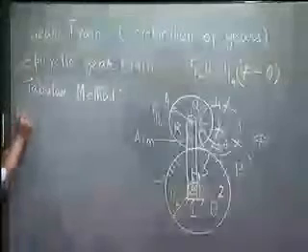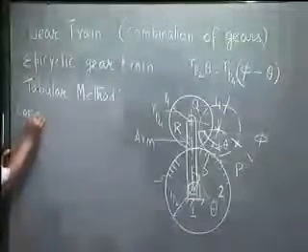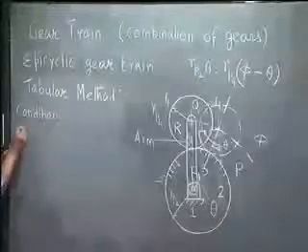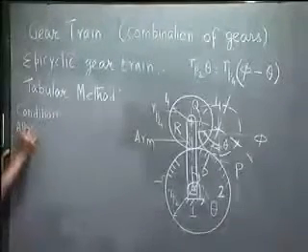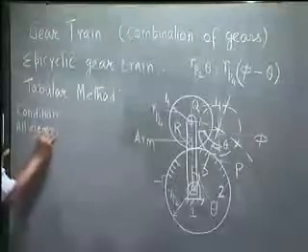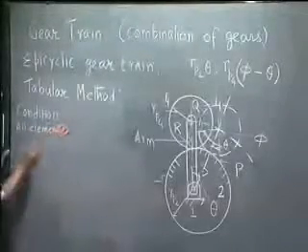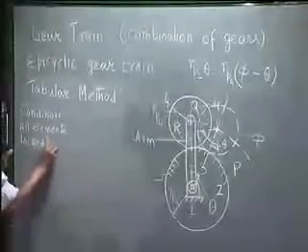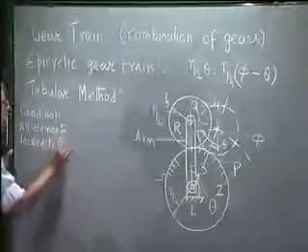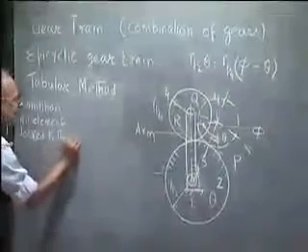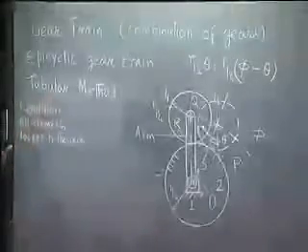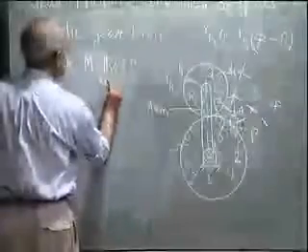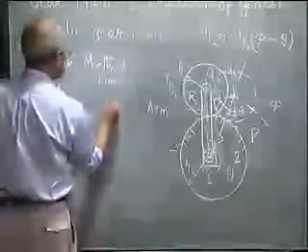And we write the condition: all the gears locked to the arm, which means the whole train becomes one rigid body, and then give the arm some y revolution.